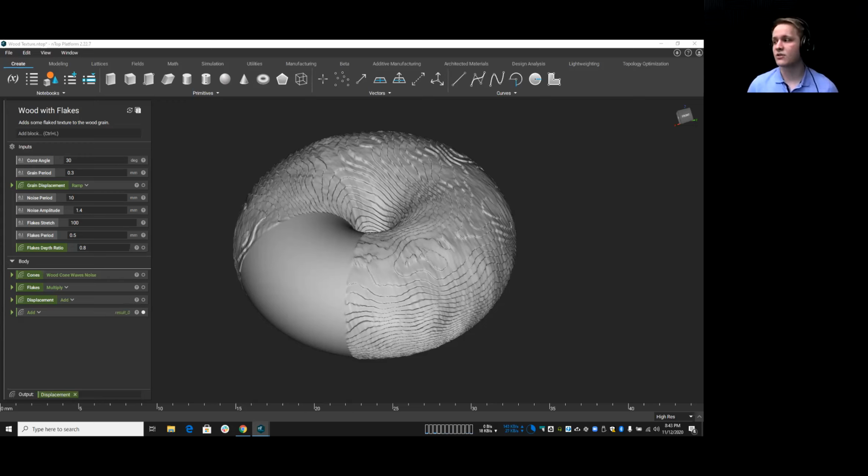What we can do is incorporate your knowledge of this process. So a couple of constraints that are coming out are going to be minimum feature size and overhang constraints. So okay, I'm printing this out of aluminum on my EOS M290. I know I can have a 30-degree overhang, but the minimum feature size I can have is 200 micron. So you're going to be able to incorporate those types of constraints directly into your optimization, but not just click, Concept Laser and have it do it for you, right? You still have to know what you're doing for the optimization to be able to run. So kind of a yes and no, but what I can say is more of that is in the works right now.